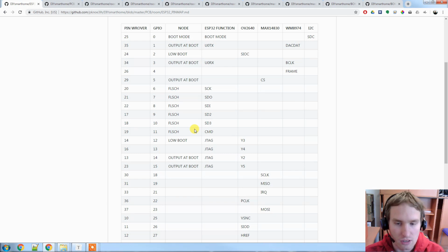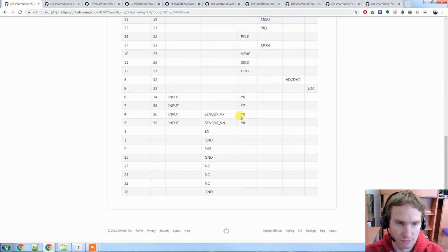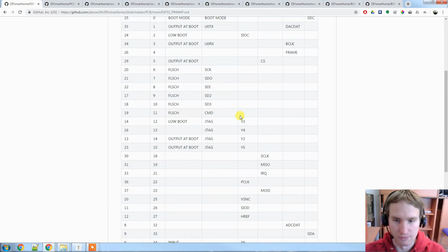We also need our SPI to UART bridge in the room sensor, so I do not have enough I/O ports to actually use the UART built into the ESP32. This is the final pin mapping for the PCB design I did. And this can maybe change in the future if we need to change something.